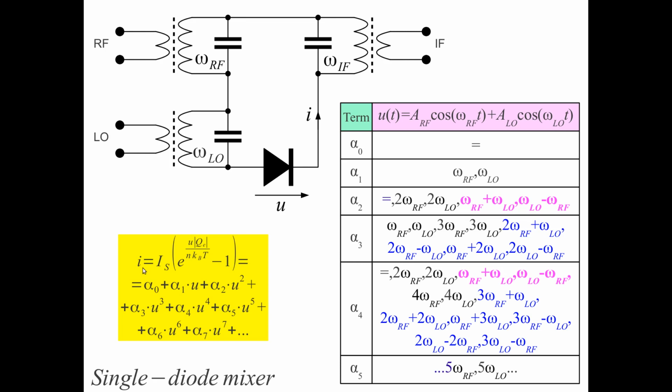So this evolution of the response of the nonlinear component contains all possible terms. So we get from the DC terms up to the highest harmonic here. And we can only pull out the desired mixing product by using frequency filters with a single diode. And this is a single diode mixer, or an unbalanced mixer. This mixer is not balanced.